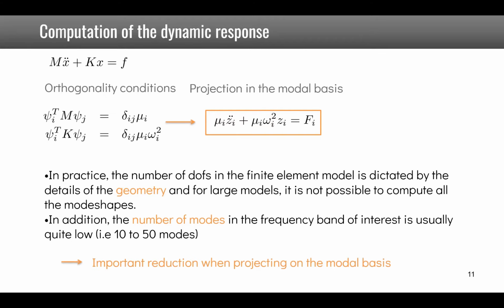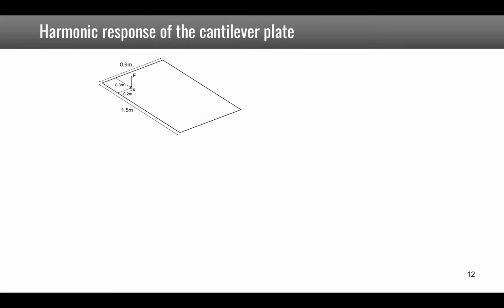So in the end, we have a drastic reduction of the size of the problem when projecting on the modal basis. This is the example of our cantilever plate, where a force is applied at this location and the displacement is computed at the same location for an harmonic excitation.